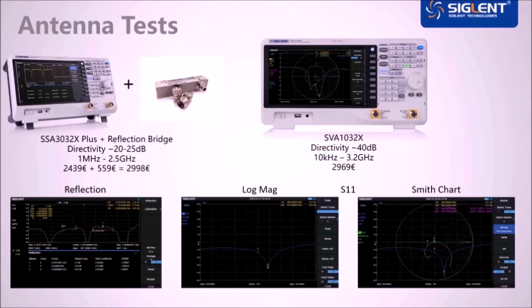One more thing. If you buy antennas, or your own design is produced by some kind of PCB manufacturer, you should always have regular incoming inspections for your antennas. I had many customers who had very bad surprises with the deviation of the individual batches and had some product recalls. Therefore, try to keep in mind that antennas should be tested frequently.